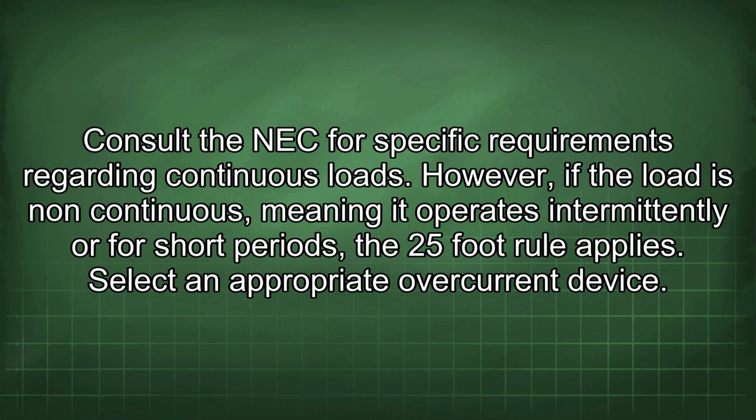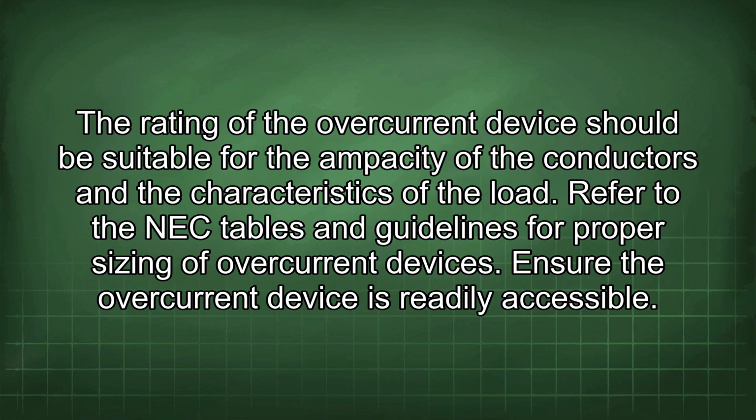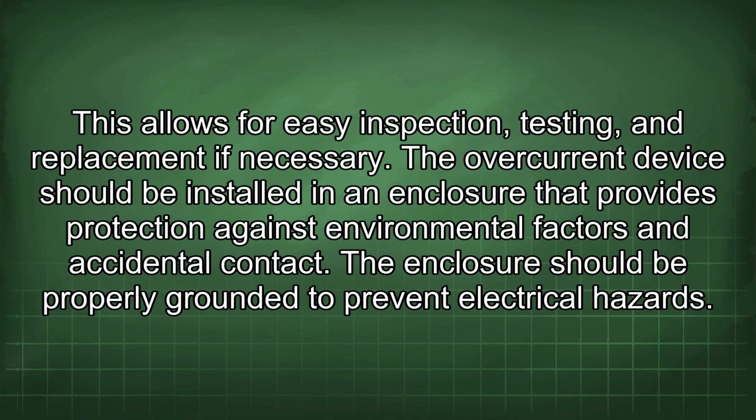Select an appropriate overcurrent device. The rating of the overcurrent device should be suitable for the ampacity of the conductors and the characteristics of the load. Refer to the NEC tables and guidelines for proper sizing of overcurrent devices. Ensure the overcurrent device is readily accessible. This allows for easy inspection, testing, and replacement if necessary.